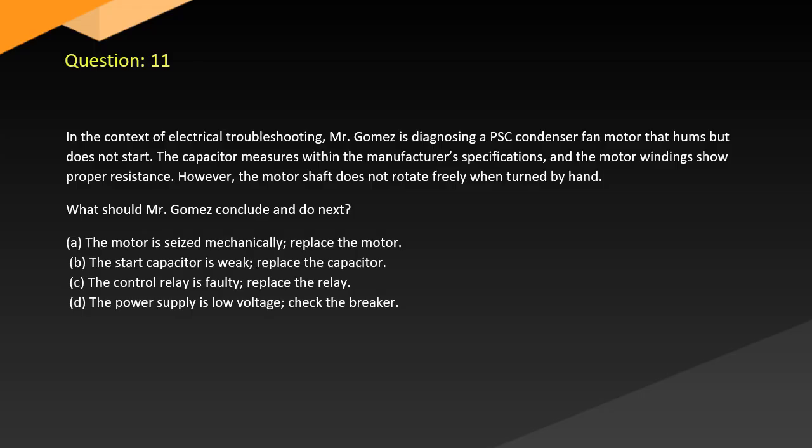A. The motor is seized mechanically. Replace the motor. B. The start capacitor is weak. Replace the capacitor. C. The control relay is faulty. Replace the relay. D. The power supply is low voltage. Check the breaker.